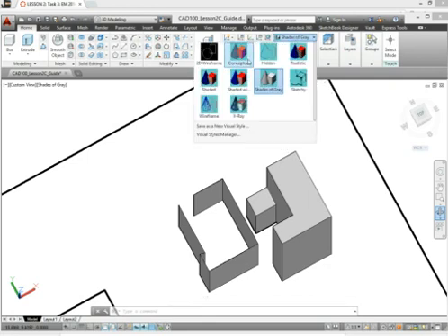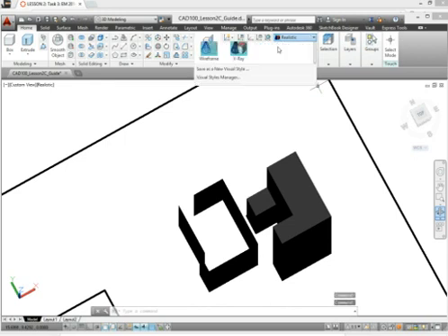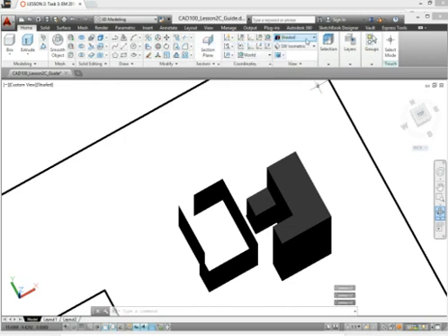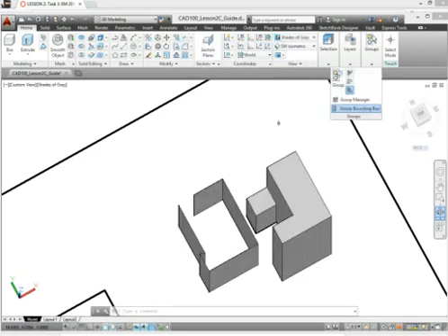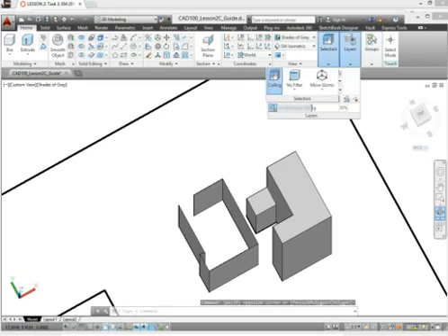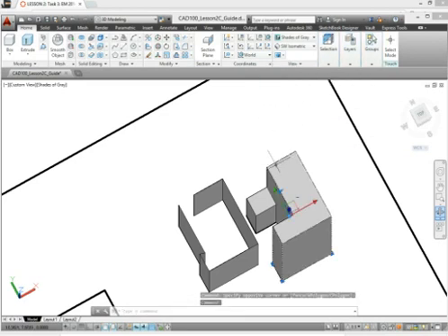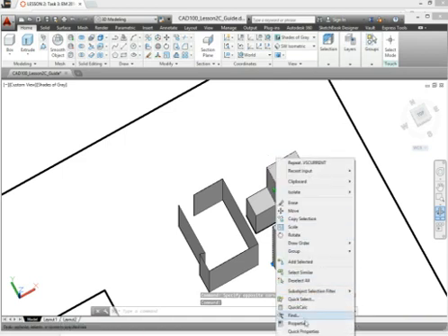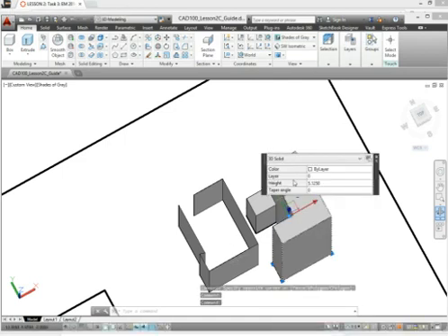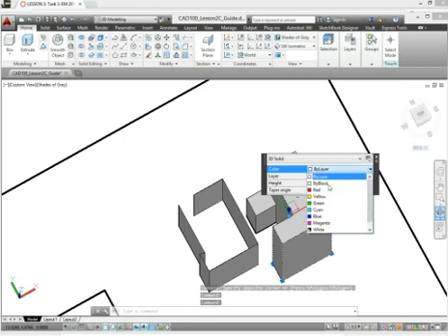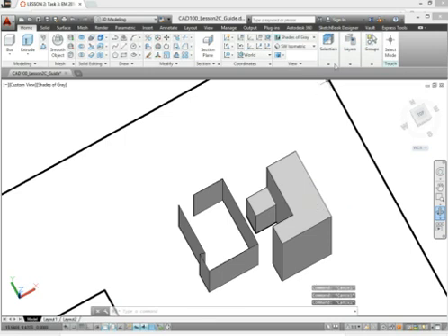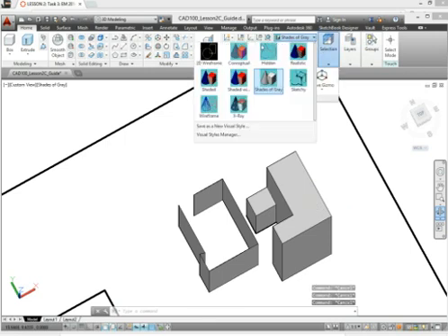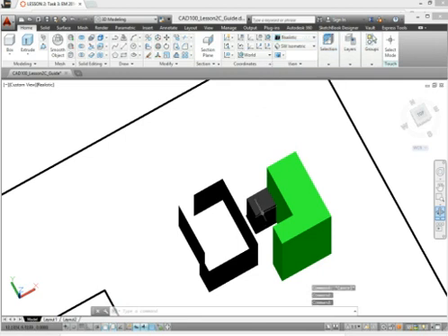Now that we have seen these commands, these are the different ways to view your object. Now the reason why everything is black is because our lines are black. So, if you want to change this color, you can go to Properties, right click, we'll go Quick Properties, change this color to something different. Okay, I'm in shades of gray, which is why you'll see the color. Let me go back to some, there you go, right there.